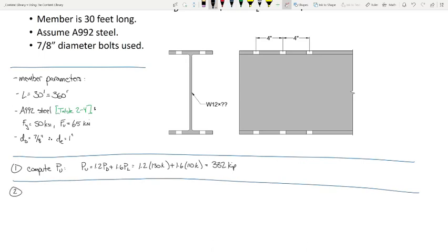The one thing I want to emphasize is that this is easy for this problem because I've given you the loads. It is possible that I don't give you the loads, but I give you the structure. I say, here's a truss, here's the loads on that truss, and we're designing that member. What are the loads on that member? Truss analysis, method of joints, method of sections to get the tensile load in that member. We are actually going to have a problem like that next week.